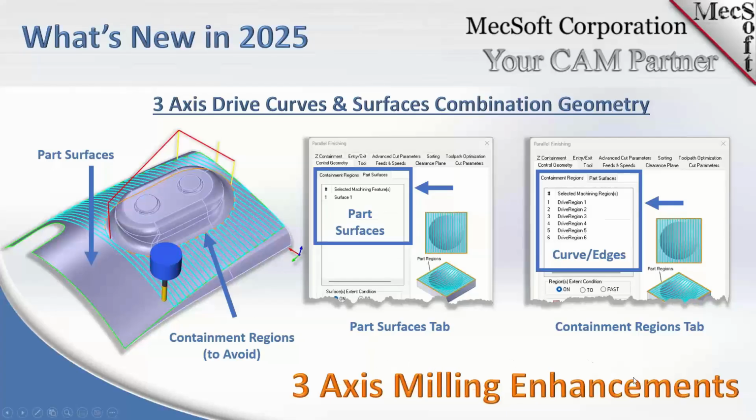Okay, so what we have here is 3-axis milling enhancements. So it's 3-axis drive curves and surfaces combination of geometry. In previous versions, you either did surfaces or you did curves. If you were doing curves and you wanted to get the same outcome, you would have to select all of the curves around the edge of the surface, then all the curves around here, and it would figure that out and cut between them. So now it just makes it a lot easier if you're going to avoid features like this in 3-axis.